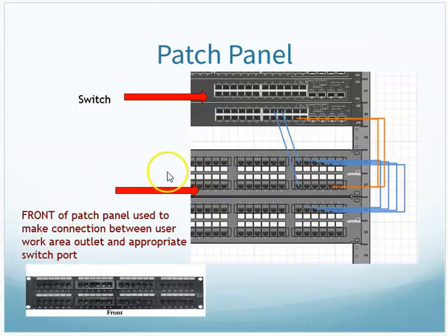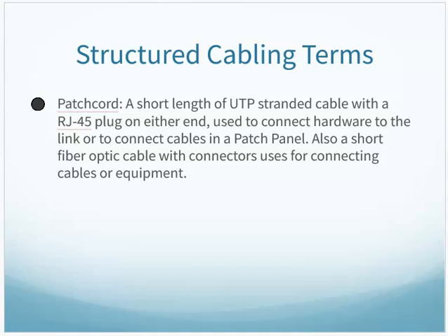And then here, the horizontal cabling is patched in the back. Now I can use a patch cable to connect from there up to a switch. That type of thing. That's what that patch panel is giving me, that interconnection point.